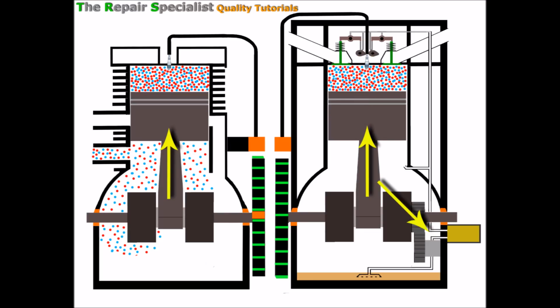And this pipe obviously supplies oil to the crankshaft as well, and generally what we find is that there's a micro hole down the centre of the crankshaft there, but the pipe normally brings up the oil to that area, and the oil is then fed down the centre there of the crankshaft to the big end bearings, and that oil is also distributed to the main bearings here.